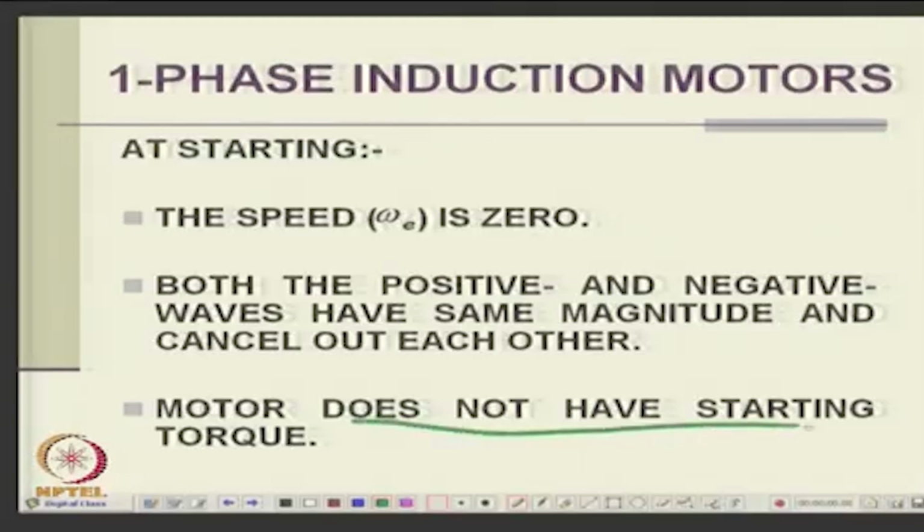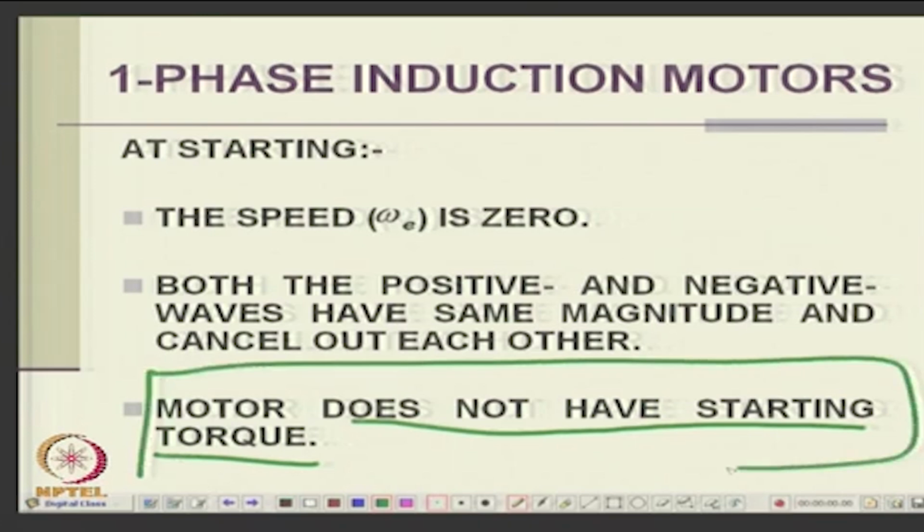One of the important things: unlike a 3 phase motor, a single phase motor does not have a starting torque. Okay. This is a very simple physical explanation. A single phase motor does not have a starting torque. And all the engineering developments have taken place over the last several decades. Initially, the problem was how to start. So, unlike in a 3 phase induction motor where there is no starting problem, you apply the voltage and it starts, here on its own it will not start, okay. So, that is the basic issue here.